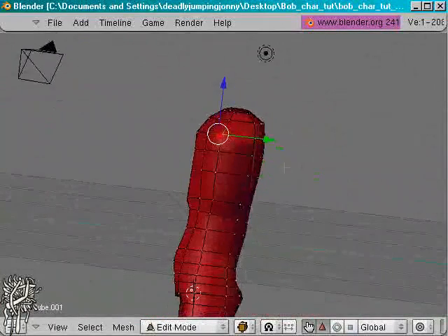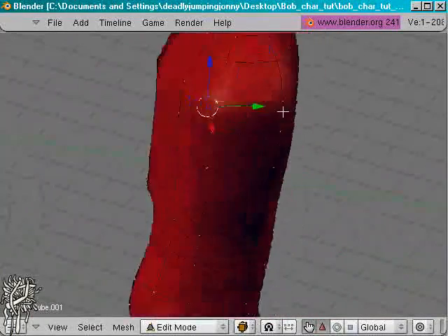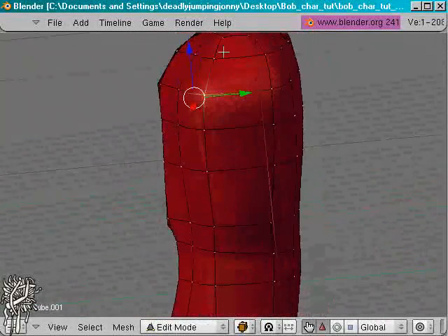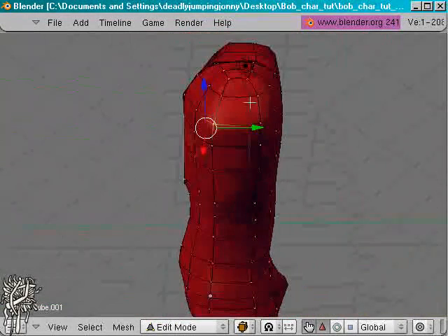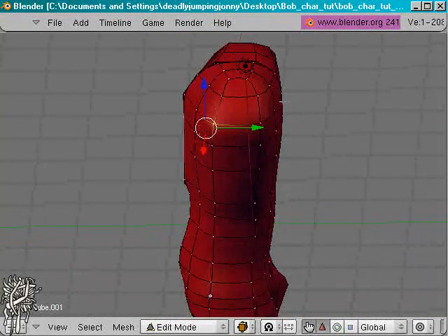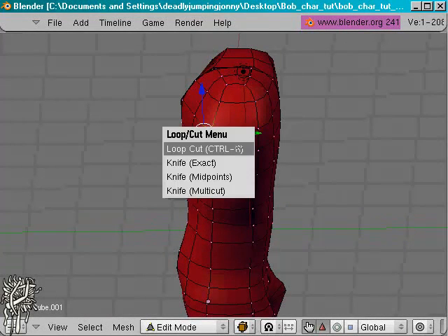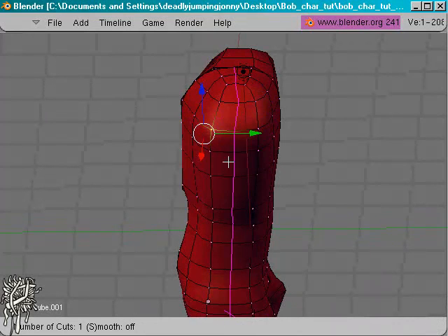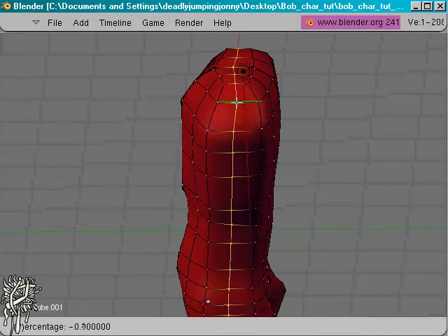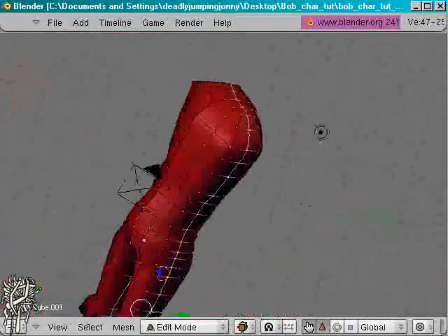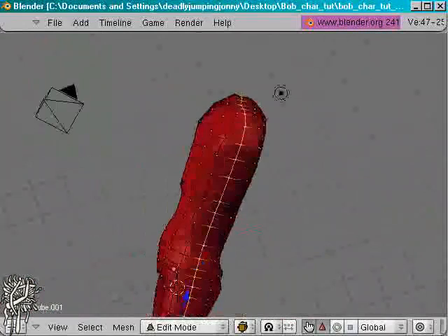Well, we're going to start on the arm now, but we're going to need to create an edge loop for the arm because I'm going to want a bit more control over the vertices. We can't really round out a square block without creating some ugly geometry, so we're just going to create a whole new loop down that side of the body. It's very simple and very handy doing a loop cut, as it's known in Blender. So go to the menu, press K and click on loop cut, or Control R like it says there, the shortcut, and that's the one we want, dead center down there. We could just move it about a bit, and then click again to confirm the operation, and we've got ourselves a nice symmetrical loop that goes all the way around.